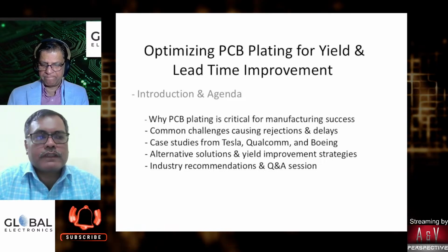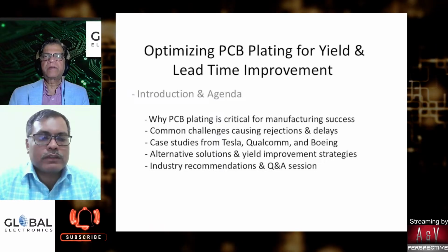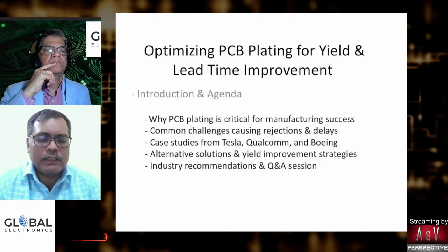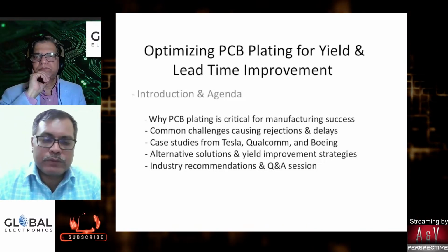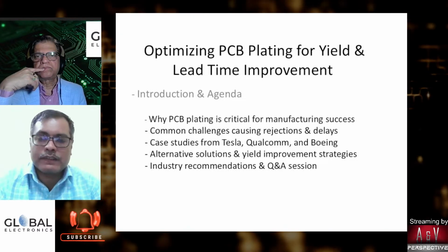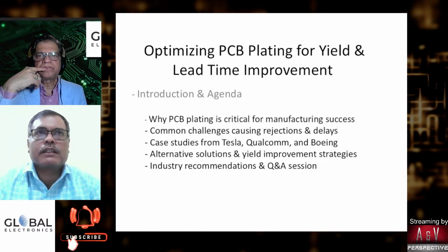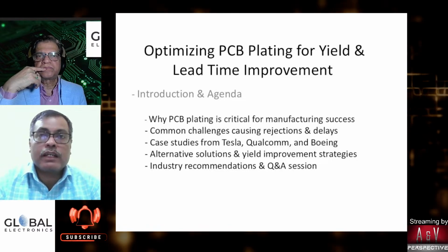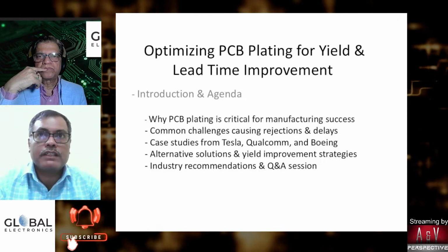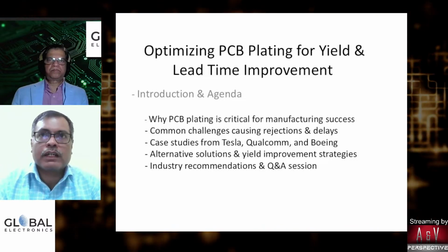For example, selecting what type of material is very important. To have that material selection, the designer has to have the thermal management in the design properly, because suppose it is a multi-layer board with a layer count around 18 layers, 20 layers like that, thermal management plays a very important role. If that is not managed properly, the board will get warpage.